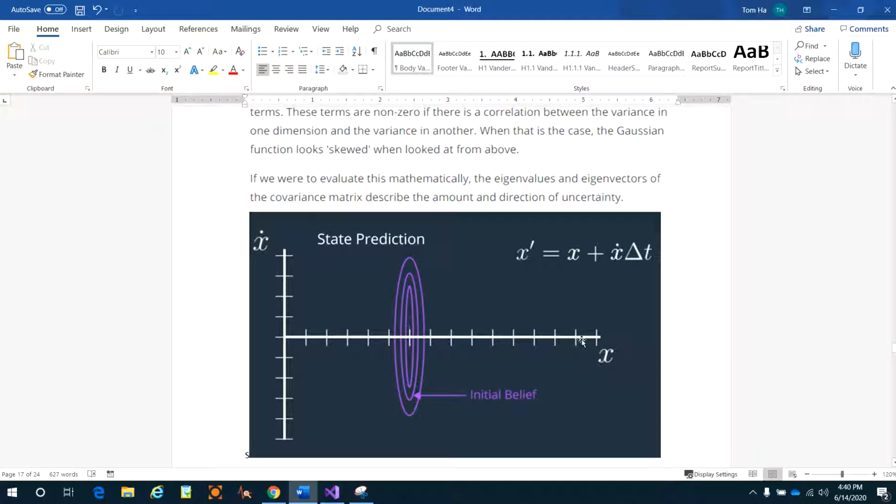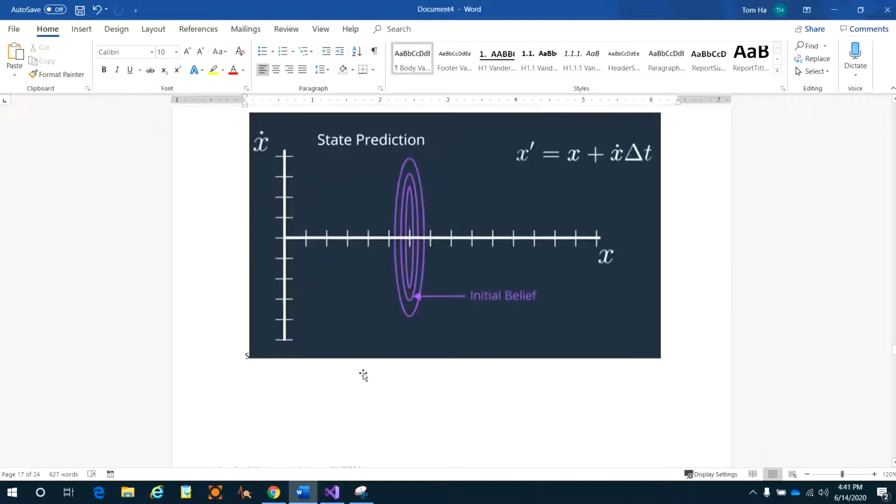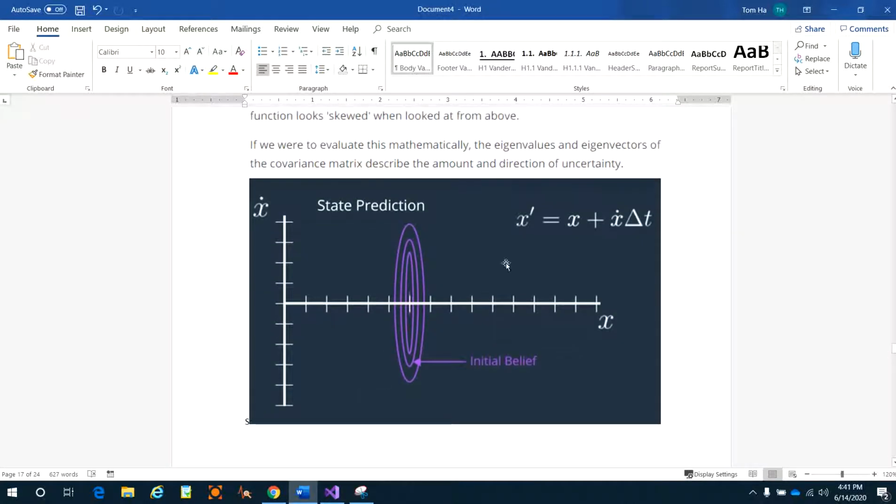It means we can measure s from the sensor, it is the observable value, but the velocity s dot is a hidden value. It's the same as in one dimension. For the Kalman filter we have an initial value and state prediction. Okay, for example, we have the motion model right here.